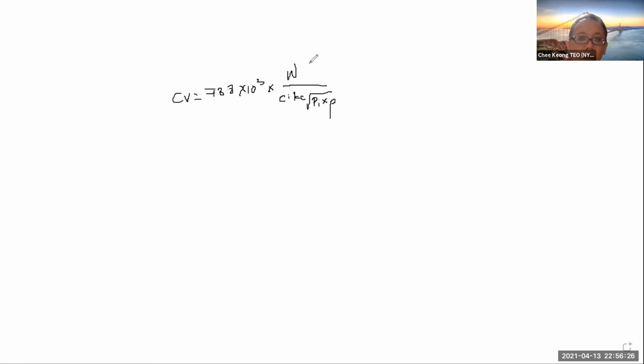Now let's find each of the components individually, right? So just now from the table, CI is equal to 35.3, using the correct type. This is from the table, right? Now, of course, the mass we cannot use directly as 1.3. So here you have to include the surplus of 150%. You have to multiply by 1.5. So the mass is actually 1.3 multiplied by 1.5.